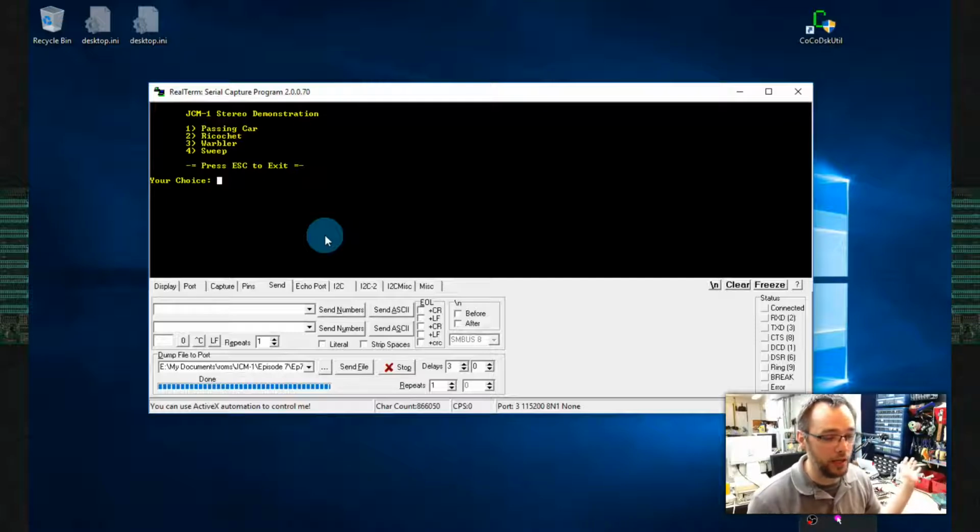Starts on the one side. I turn the sounds on at a certain pitch, and I let the envelope bring it up to volume. Once the envelope has brought it all the way up to volume, I then sweep both the pitch and the pan, the pitch and the stereo, effectively using the same register value from 0 to 255. Yes, from 0 to 255, which both brings the pitch down, because when you make the number larger for the sound generator, it has to wait that much longer between making pulses for the sound. That's basically how the sound generator works. And also, when you go from 0 to 255, that goes from left, 0 is left, and 255 is right. And so it pans them both simultaneously.